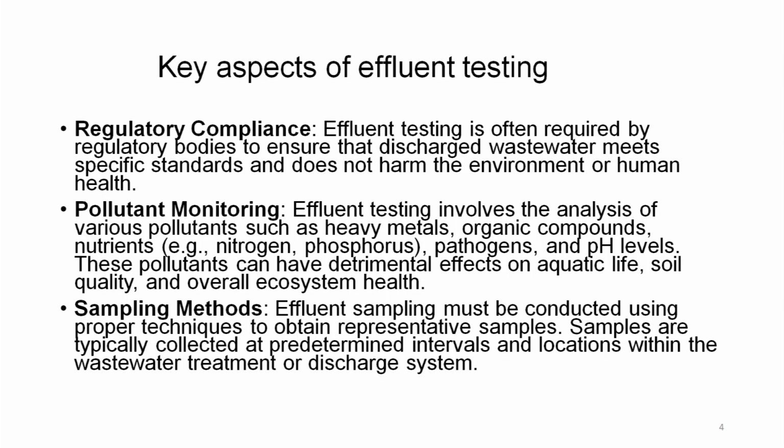So, even the sampling has to be done very systematically. It is not that one can do any random sampling, keep it for days and then analyze. The sample will get further deteriorated and we will get different results than what exactly existed in the effluent at that time.